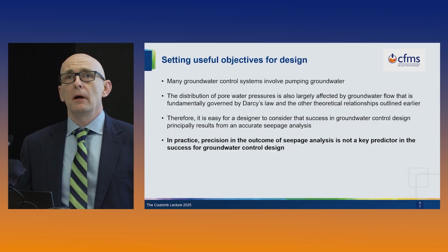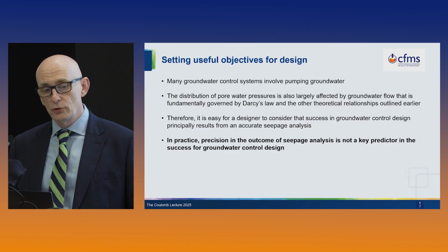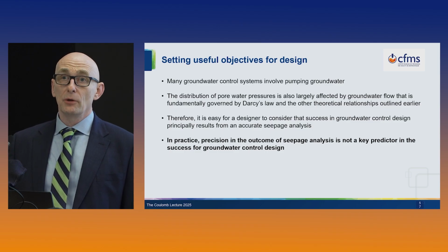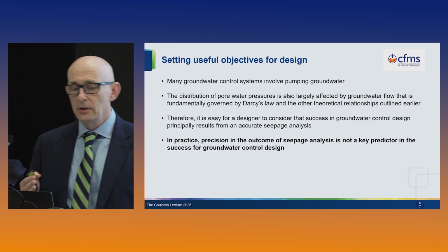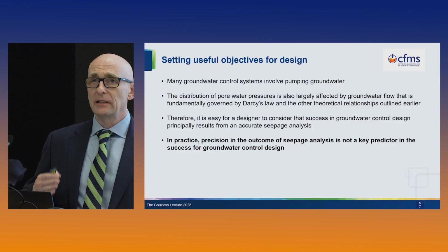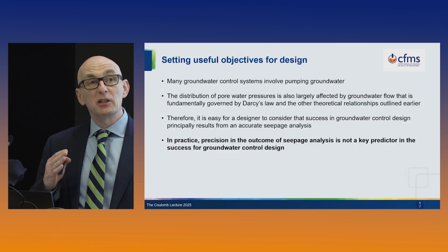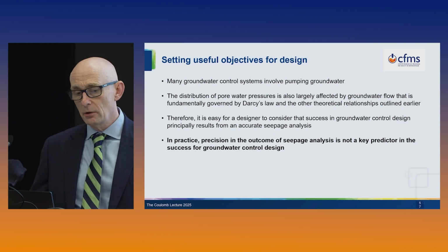So with any design or any system, you need to have an objective. What are you trying to achieve? And groundwater control systems, the vast majority of systems, pump groundwater in some form. And if you think about things like Darcy's law and other mathematical equations, broadly speaking, a ground control system is a seepage problem. We're going to analyse it either in spreadsheets with Darcy's law or maybe a numerical model.